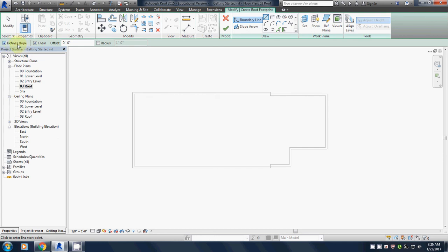So with that checked, we are going to come down here and we're going to choose the left point on the south wall, and we're going to draw out along here until we intersect, moving up here to pull that down. We're inferring to this intersection of the horizontal and vertical line, and we're going to click. It should be 56 feet 6 inches.